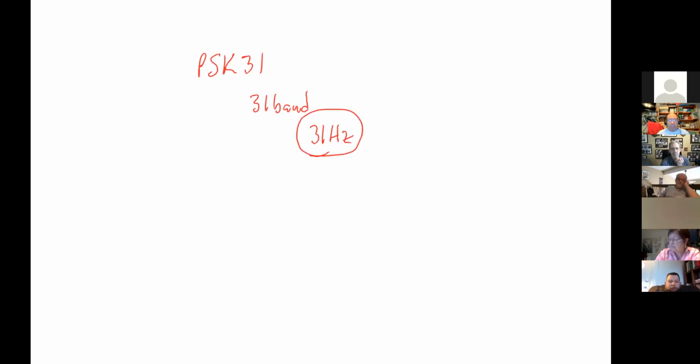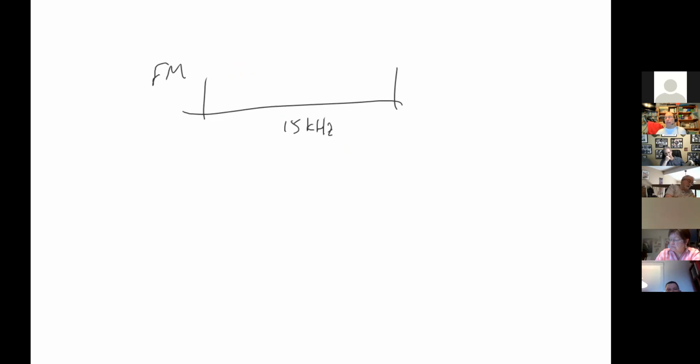Digital mobile radio is DMR. And this is a technique for time multiplexing 2 different signals on 1 channel. So remember we said an FM channel takes up about 15 kilohertz. Well, in theory, you could split it up so that there's the low part and the high part, but you'd basically kill your fidelity, and you'd have to come up with a different transmitter for each one. What we do is we say that for part of the time, these guys get to use it.